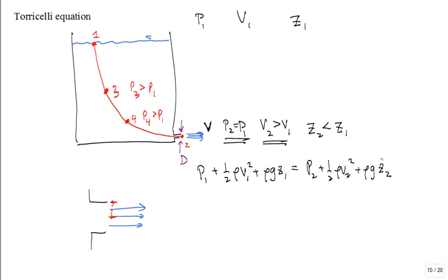All right. So we cancel these two because they're the same pressure. We cancel one of the velocities, not V2, that's the exit. That's what we're looking to calculate. But V1 squared is really small. Does that have to do with the area being so large? That's exactly right. The area of this tank, you draw it large, and the diameter of the tank is much greater than the diameter of the hole. You want to put a hole diameter right there.